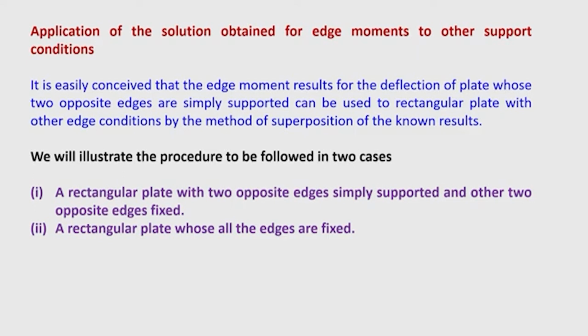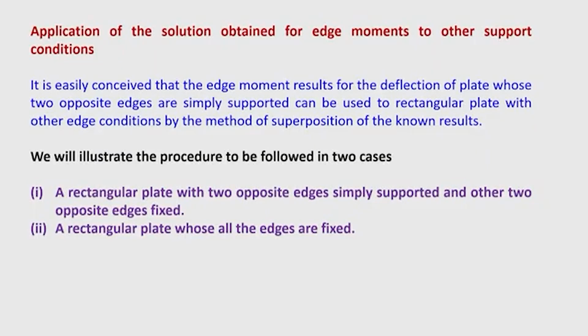So, we will use Levy's method for edge moments, symmetric as well as antisymmetric, and apply it now to a plate which has other support conditions not directly following Levy's condition. Okay. So, let us see how it can be done.